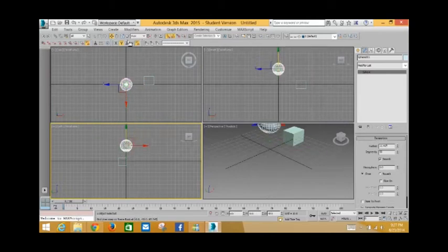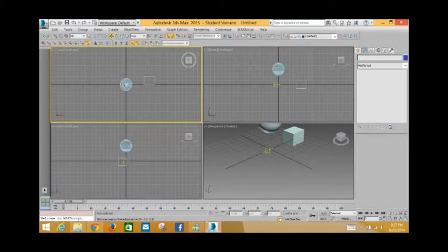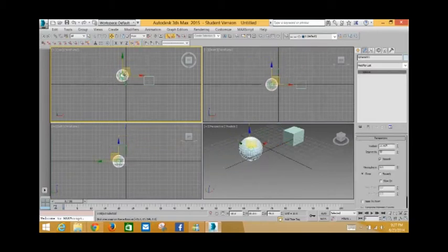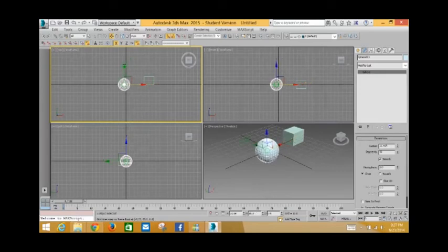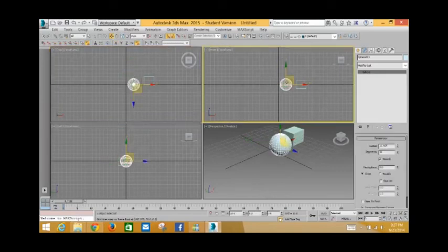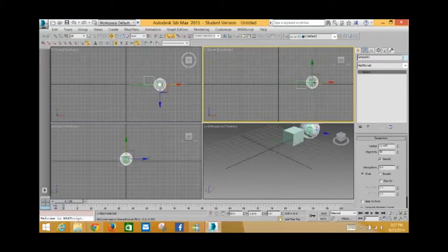Or you can combine axes that you want it to move along. In this particular case, I've got it set to ZX, so it'll move either along the Z or the X. Wait, I lost it. Here. That's XY, so that'll allow me to move along either the X or the Y axis.